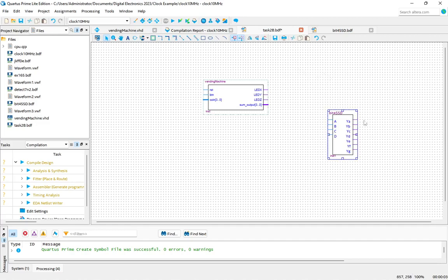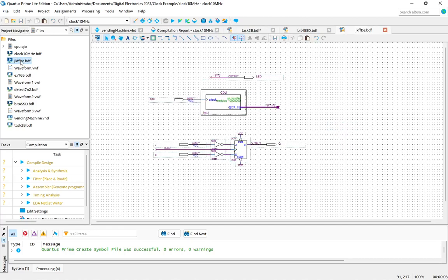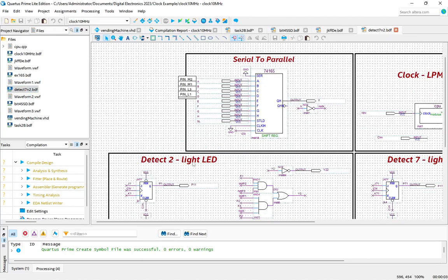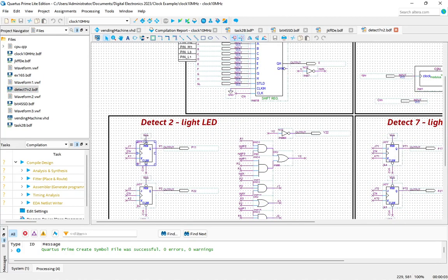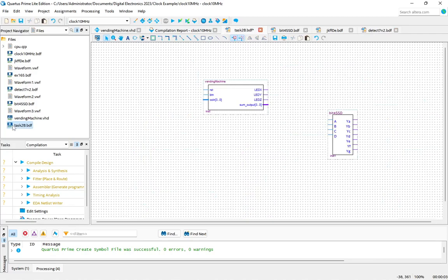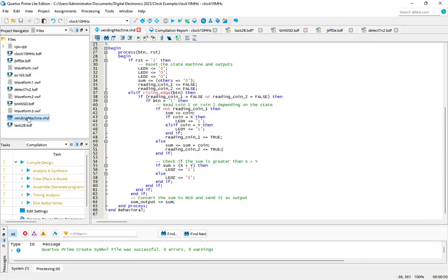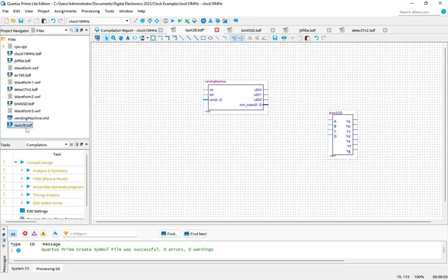Here you design a JK flip-flop, so you convert that into a component and then you use that component on your sequence detector. Like here we've defined a component and then converted it into a block diagram that we can use on all the other objects.